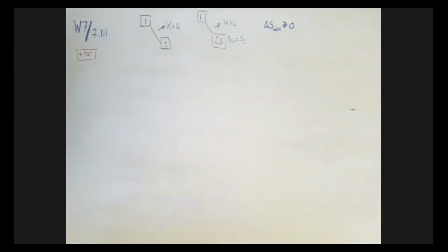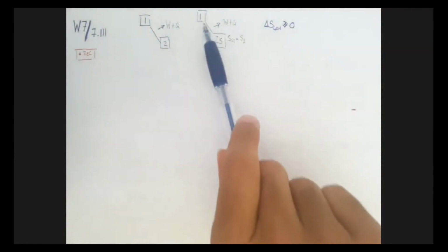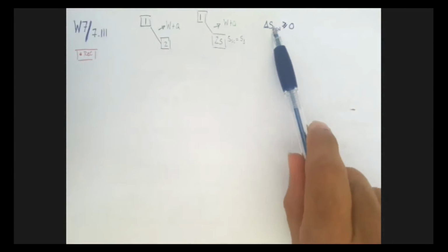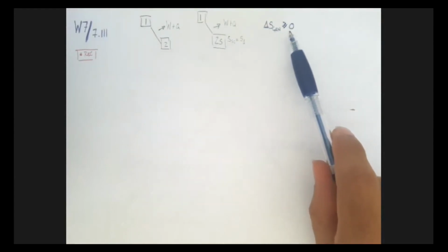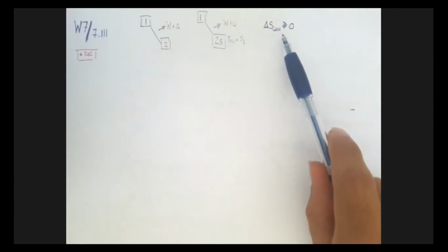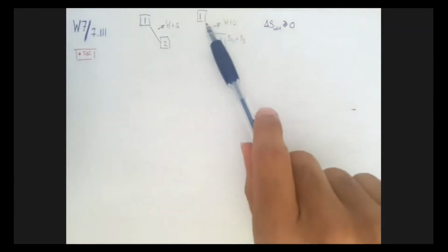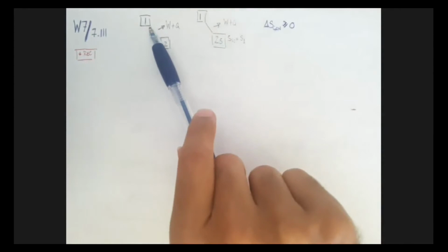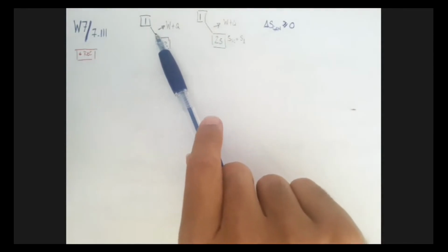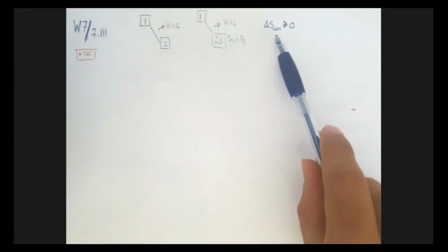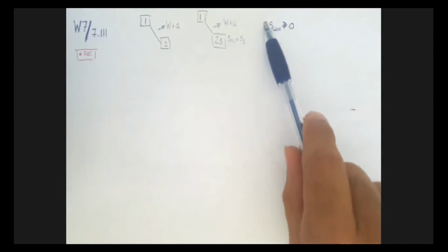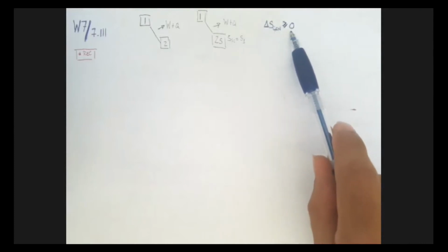What do I mean? If we have a fully reversible process, which is this imaginary case here, my entropy generated will be 0. I haven't increased the disorder of my universe. However, if I have a real, actual case, then I'm going to have irreversibilities, and therefore an increase in entropy. I'll have generation of entropy, and my entropy generated will be greater than 0.